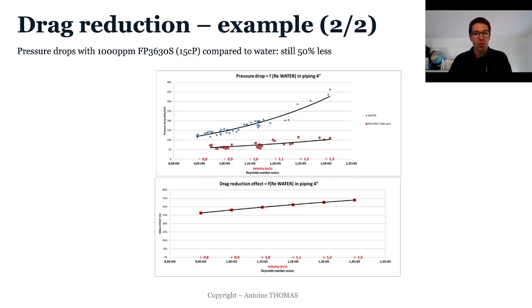If you switch at constant rate between water and polymer at low concentration, it's very likely that the first phenomenon you will see is a pressure decrease, just because of this effect. If it's not taken into account, you might wonder what's happening, while it's just something very normal which is being used in a variety of industries.